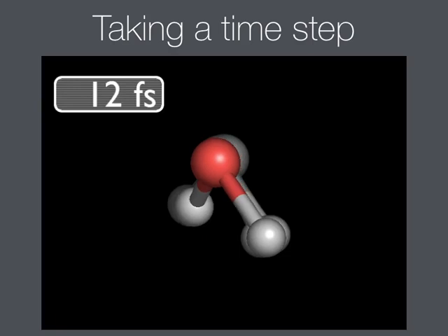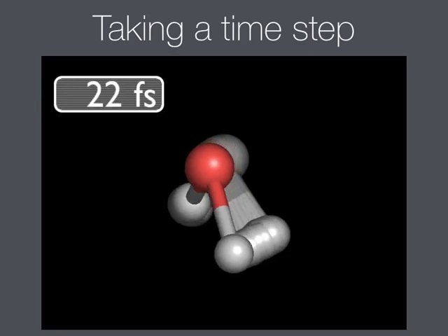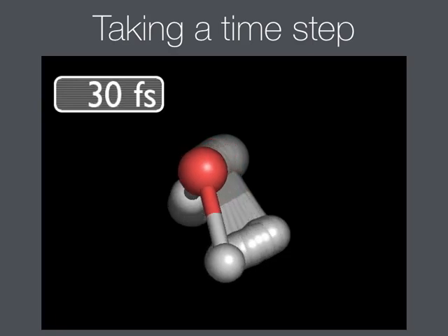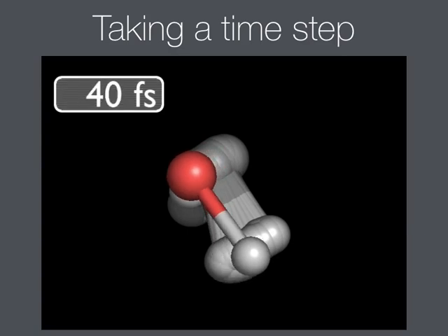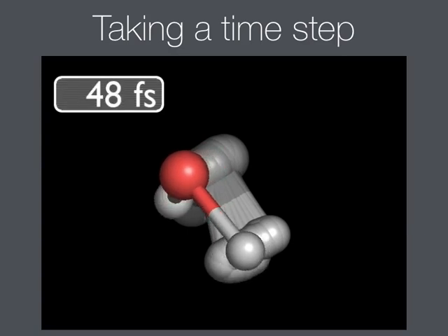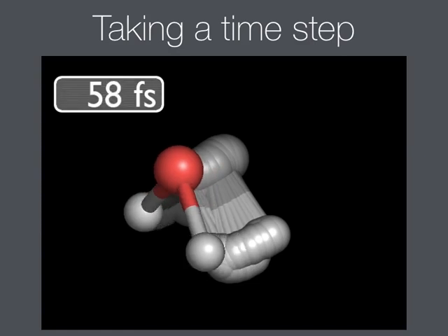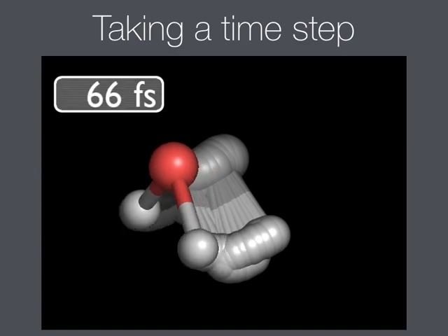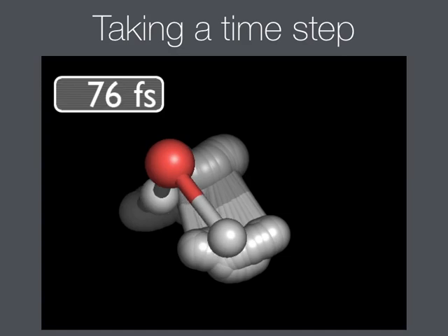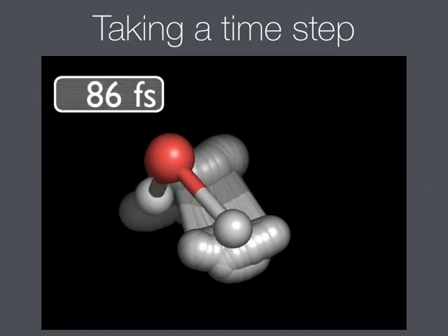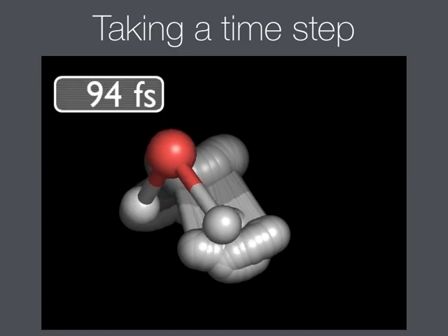Okay, so then we can actually look at how a simulation looks like. You'll see that more next week. But here's an example of a single water molecule with time steps. So the time step is 2 femtoseconds to be able to integrate collisions between atoms. So you can maybe go to 4 or so for this particular water case. You could push it a bit, but you see that this is rough. So this molecule goes back and forward because actually there's water around it everywhere. So it's not a single molecule, but I show only one just for clearness. If it would be a single molecule, it would just fly on. So you can see that it bumps and it goes back and forward.